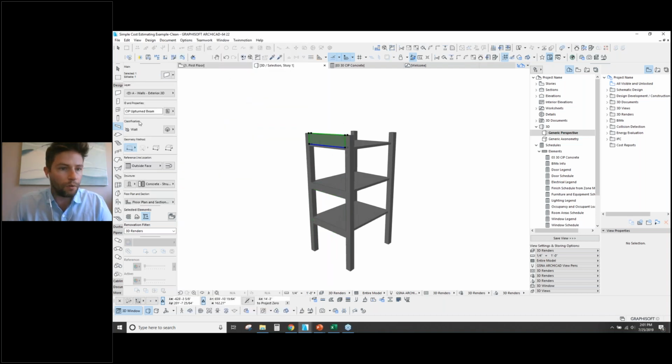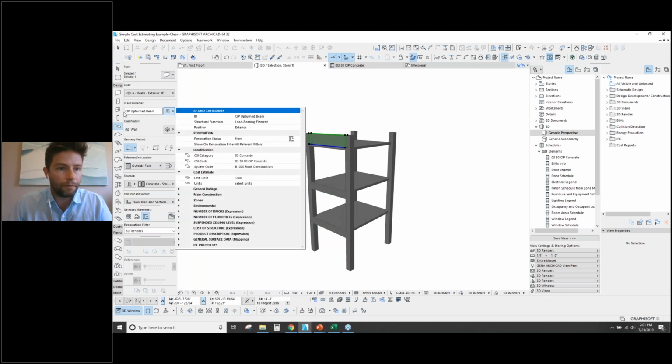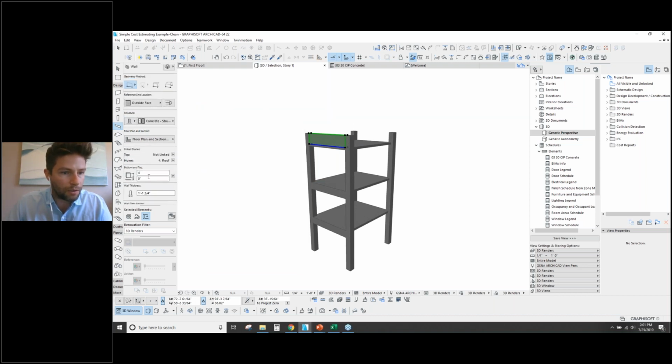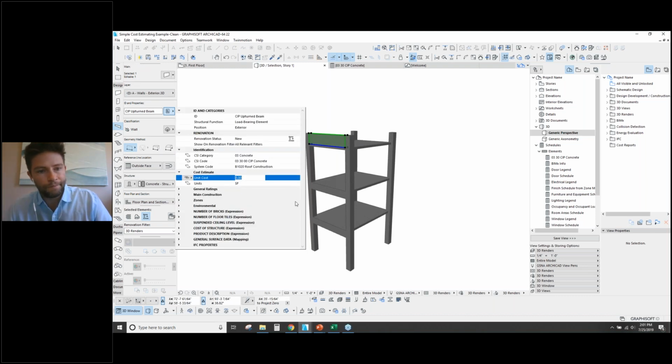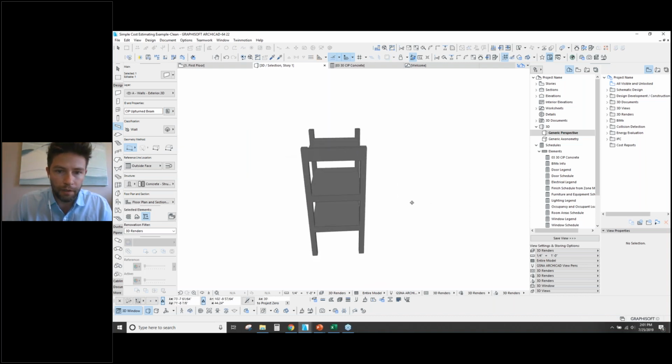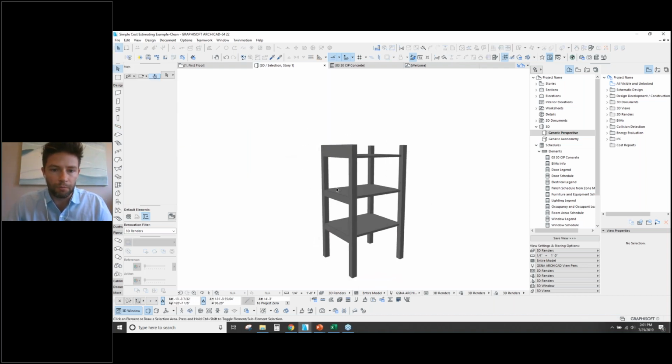And then we have a wall that's drawn as an upturned beam. So maybe we'll just do this off square footage. What's the thickness on here? It's only a little more than a foot thick. So let's just plug in probably $12 a square foot for that element. So we're just throwing some rough numbers at this.